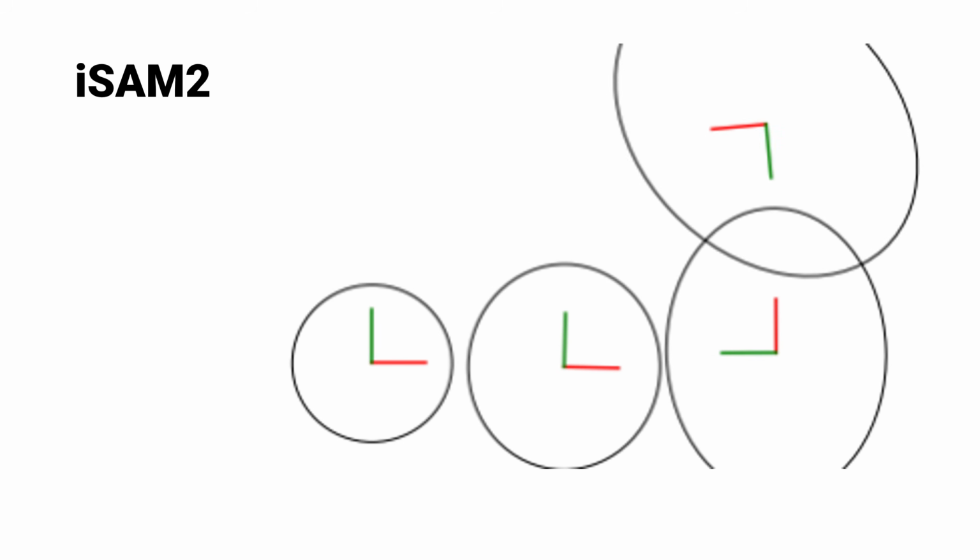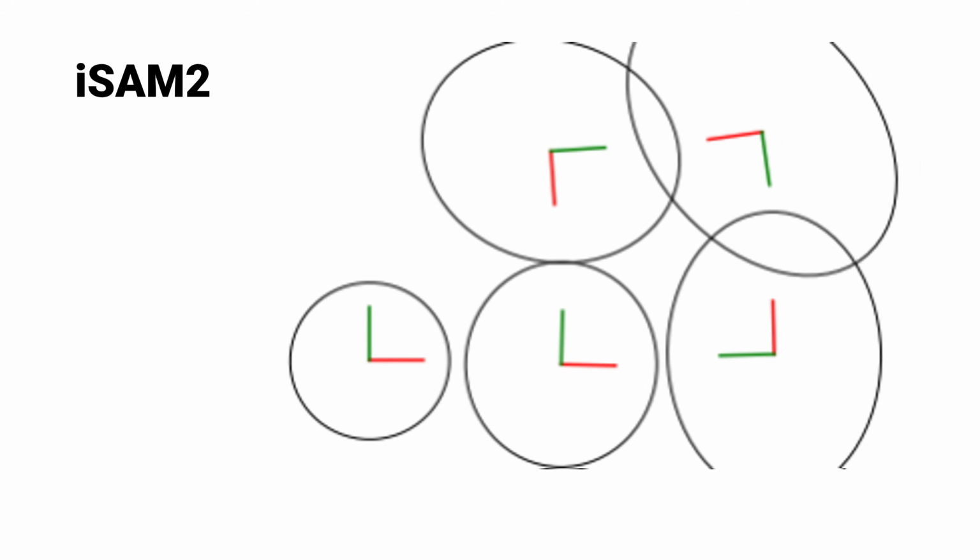In what we were seeing before, the full factor graph, you were trying to optimize the entire thing. In this particular case, your robot is moving from time 0 to time 1 through the odometry step. As you keep moving forward, you observe more observations and you get better and better. Here you'll see these ellipses, which are basically representing the covariance matrix. The larger the ellipse, the more uncertain you are about that position. As you will see, as we keep moving around, the last point will basically be the prediction, so it will have the largest covariance matrix. As we move around, the covariance matrices of the steps will keep reducing, right? And once you do take multiple steps, you'll see the covariance matrix actually reduces.